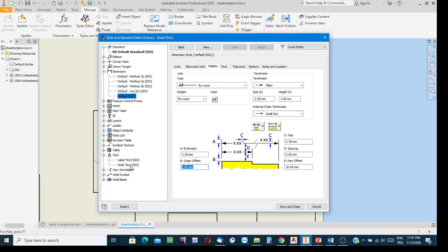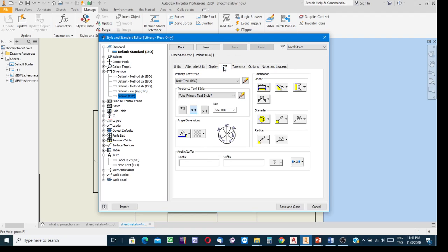At the beginning of extension lines, 2-3 mm empty space is needed. Okay. Well, for the successive dimensioning rows, the minimum distance is to be 8 mm. Well, the first coming dimensioning row with respect to the utmost boundary is 10. These are correct. Size of the arrow 3 mm. Clicked on save button. Okay, and then text option.